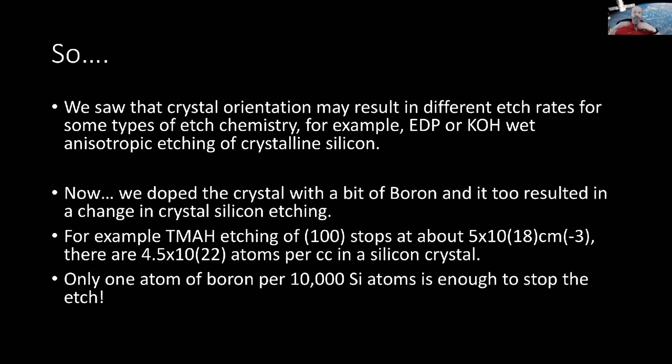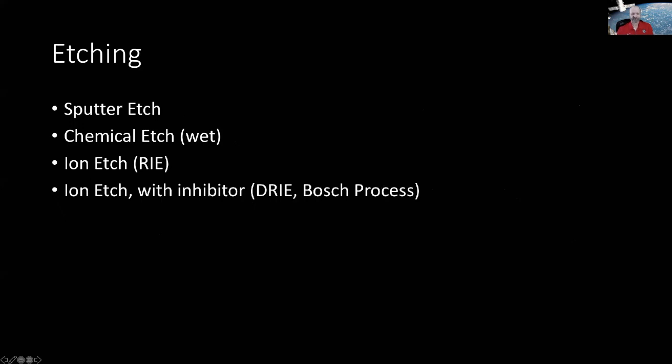The mechanical properties of that membrane are the same as if it was pure silicon, but the chemical properties of that material are completely different when it's related to etching. And also it's different when you consider electrical properties as well. Okay, so a small amount of doping can radically change electrical properties and chemical etching properties, but it kind of leaves the mechanical properties alone. So that's something to keep in the back of your head if you ever work in this. Okay, so I'm going to stop here, and we're going to talk a little bit more about etching next time.